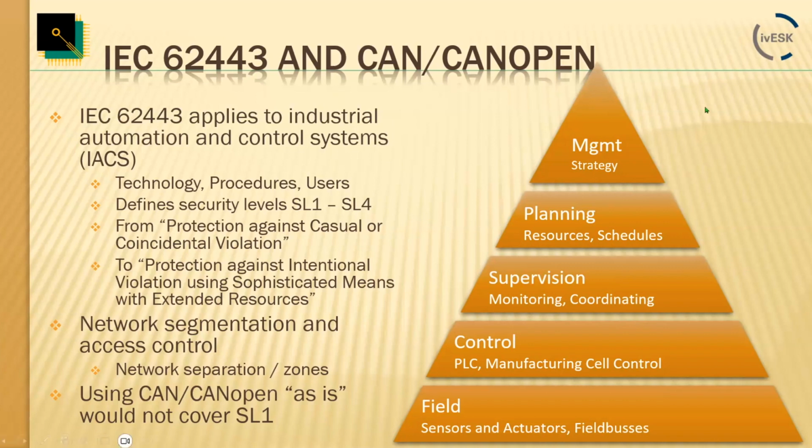So if we look into the traditional method here of the automation pyramid, then we can see that CAN-FD is typically here somewhere in the lower layers. And wherever you interface with any of the other layers and other networks, always imagine a little firewall here where you have to carefully select which data you want to make accessible across borders.